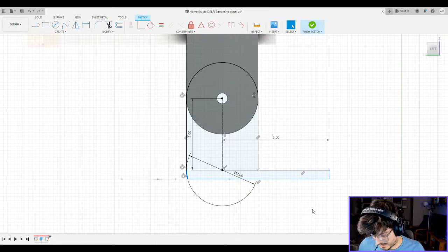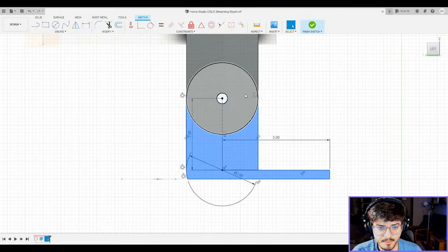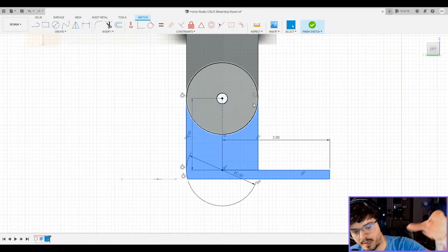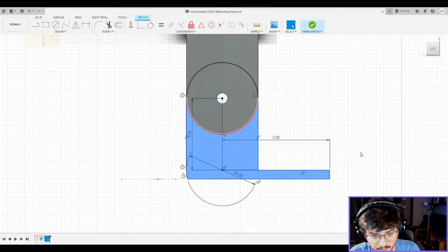So I was thinking again, if I have it like this, and it turns into a springboard, that's a good layer line direction with weight distribution. And then this large part back here ends up being nice and flat. So again, the screw is compressing the layer lines, so that's good too.